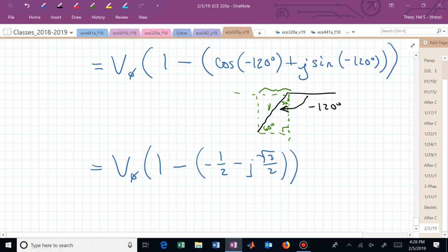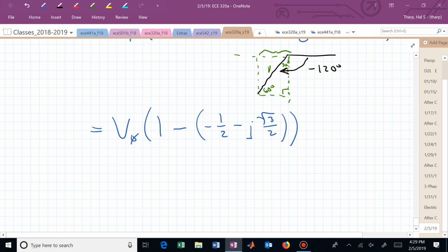But that's how we know this is now v sub ab. But we can clean this up. That's just a complex number that's weighting a number. And that complex number has a magnitude and an angle. And that's going to now adjust the magnitude of our phase voltage v sub an. And that will be our relationship between our phase voltage and our line voltage. What does this become? Now we have v sub phi. We have 1 minus a minus 1/2. This is really tough, isn't it?